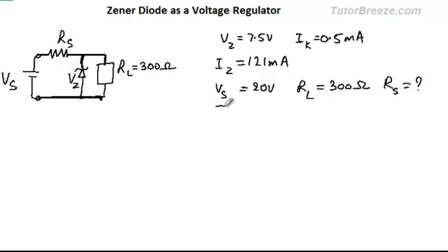We are given that the current through the Zener is 1/4 of its maximum value, which would be about 30 milliampere. See, we are given this value of current because for this current the Zener is most stable and the voltage remains more or less constant, because we are operating in the linear part of the graph. So it will give us the best output. So it is given that the Zener current is 30 milliampere, and now we need to find the value of the series resistance.